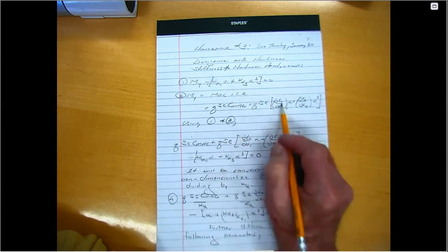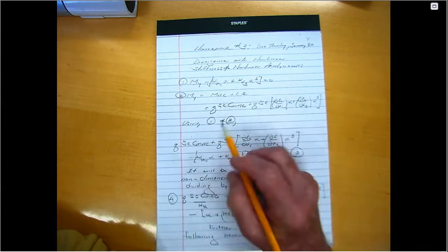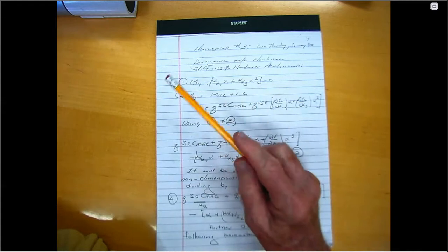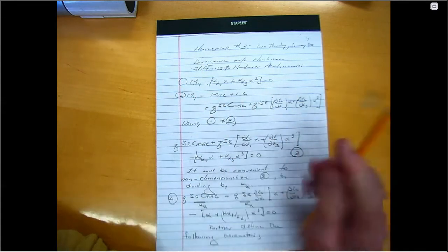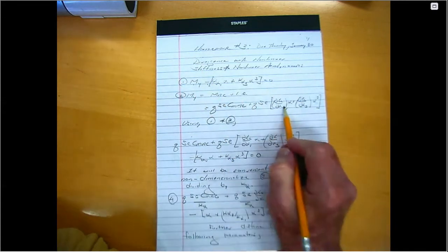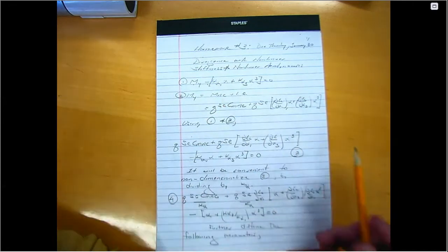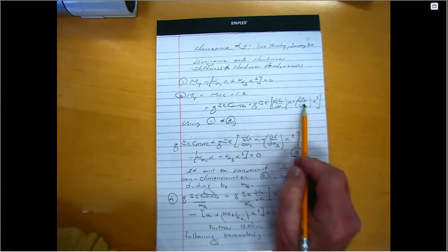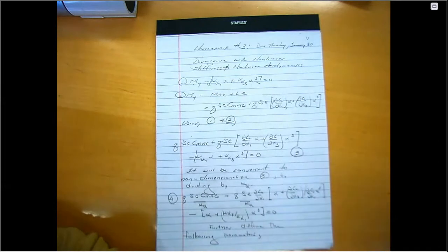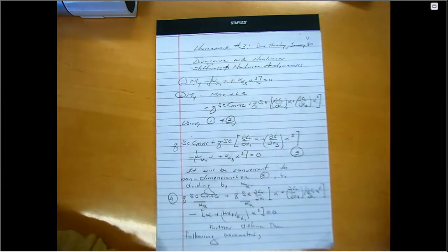Then this is the non-dimensional form of our aerodynamic lift. We have a linear term, and we also inserted another term, recognizing that physically this coefficient is normally negative because the aerodynamic lift decreases as you get to a larger angle of attack.